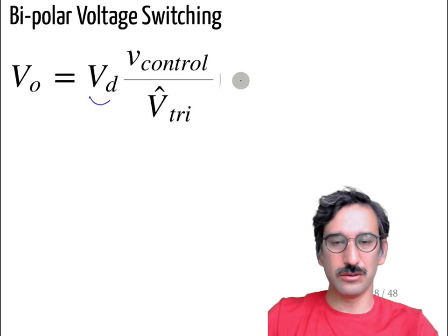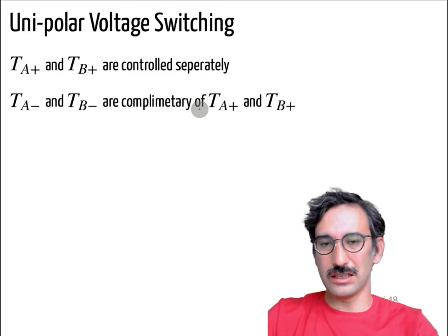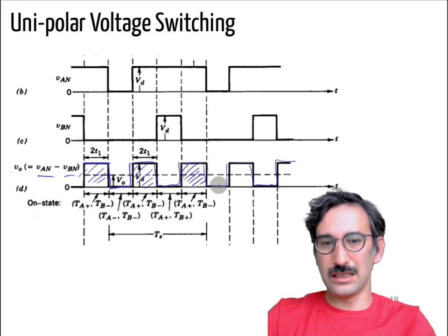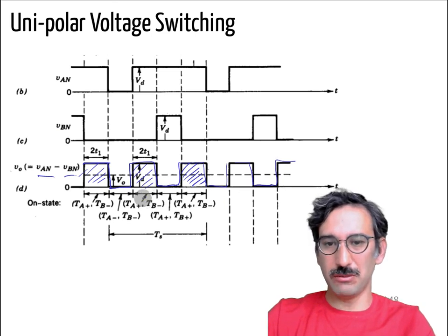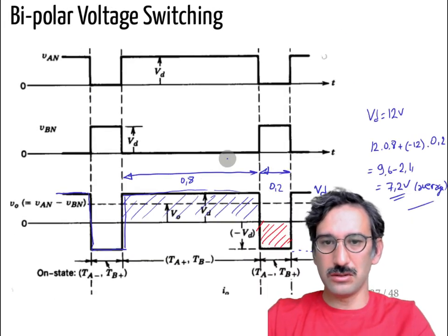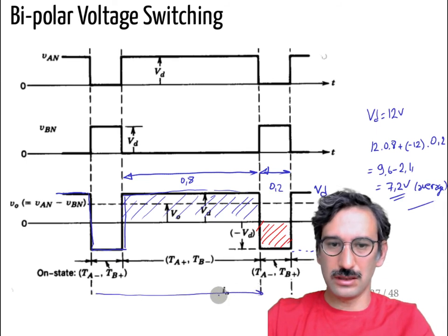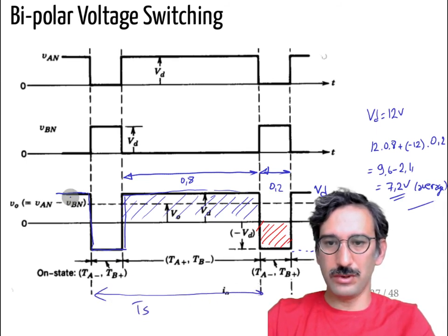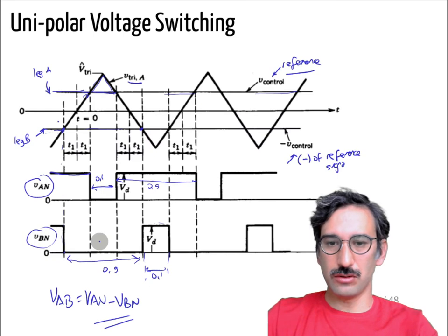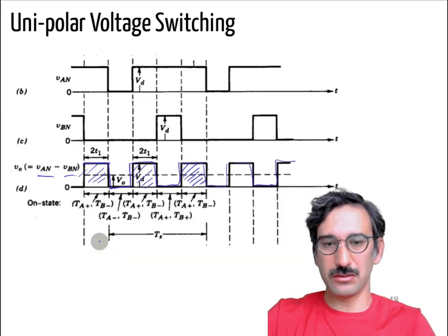Okay, so you can do both of those things, they generate the same voltages, but the second one has less ripple. Why? First of all, you don't go down to negative voltages. And secondly, let's have a look at the voltage waveforms here. So this was your TS. Okay, so VIN becomes one negative and one period for positive. If you look at your unipolar here, it is as if the switching frequency is doubled, right?